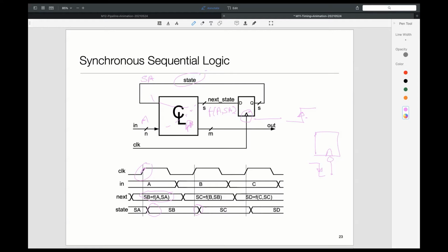Now, we already previously saw how voltages don't change instantaneously, right? All of these things take time. So a couple of things stand to reason. Firstly, there is always some delay after the clock tick, right? The second thing is, for all of this to work, my input to the state register needs to be stable before the clock tick, because the clock tick is not an instantaneous thing. It takes, if you're lucky, some tens of picoseconds or something like that, but still takes some time.